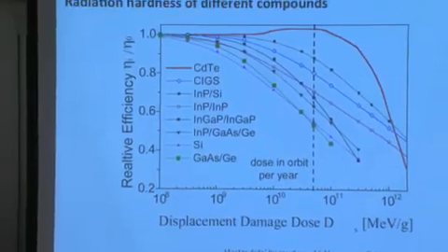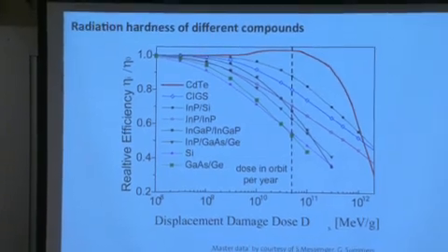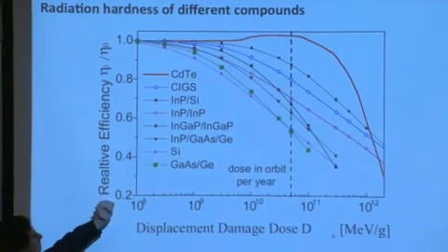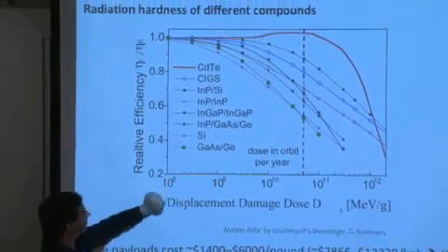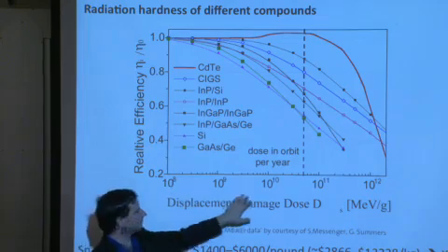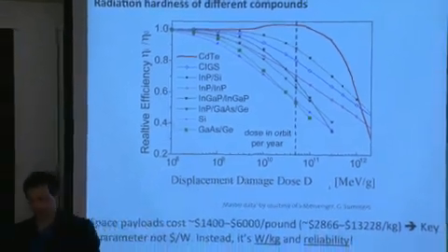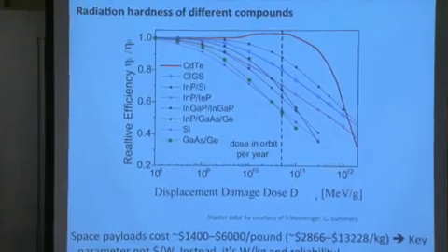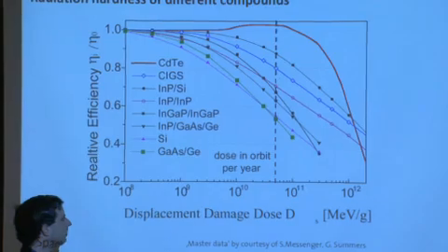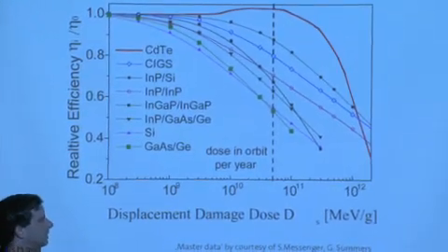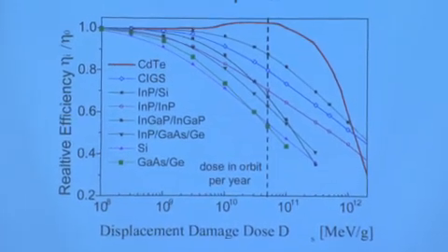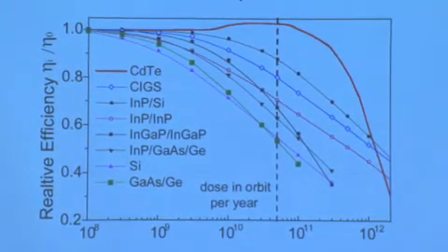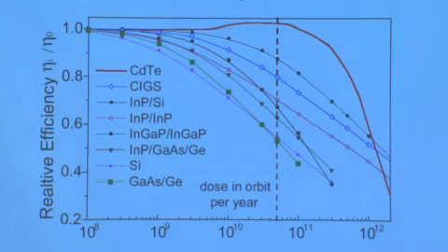And finally, radiation hardness. Getting back to Ashley's question, gee, what are the most radiation hard species? This is the efficiency of solar cell performance normalized at the very start of a test. And this is the equivalent radiation damage. You could also think about this as the amount of momentum or energy transferred to the atoms inside of your semiconductor that would result in lattice damage, that would result in a decrease of minority carrier lifetime or mobility, which ultimately would impact cell performance and efficiency.